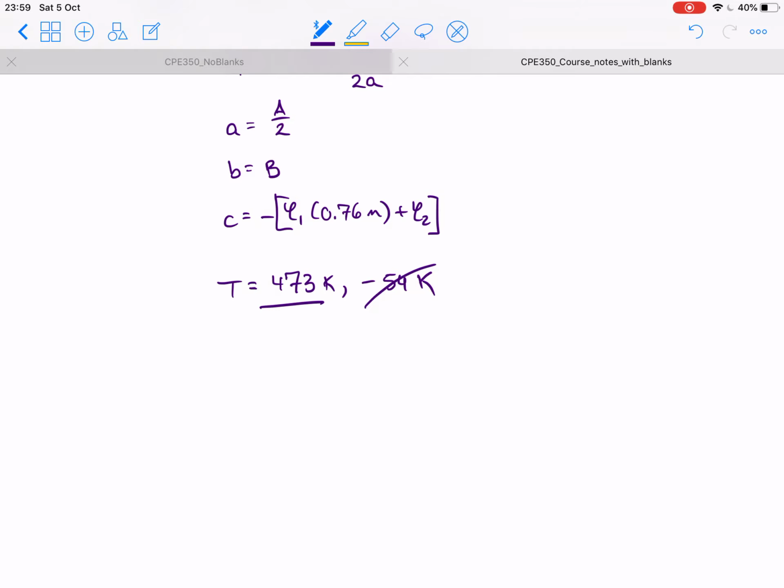So if we were to put this pipe in, making an approximation for the thermal conductivity being constant, we would aim to have a temperature of 400 K, and we would actually get a temperature of 473 K. So you can imagine that amount of superheating could actually cause a lot of damage to the pipes because you would have a much greater pressure duty than you expect.